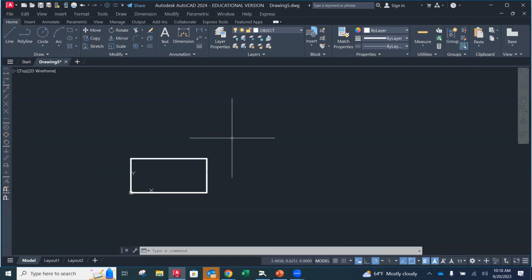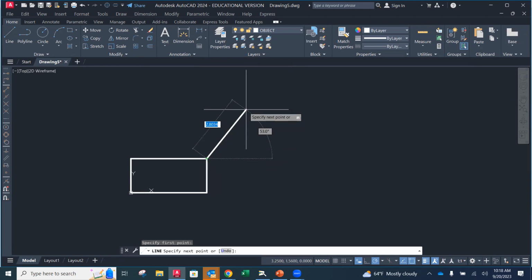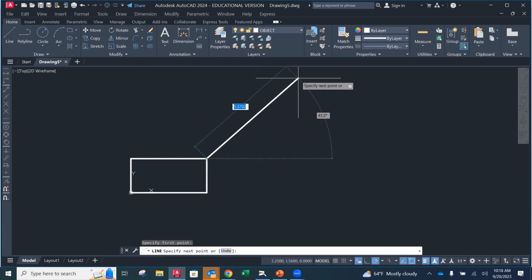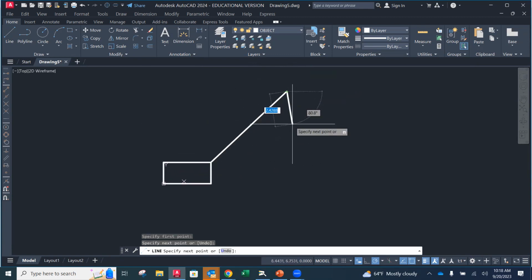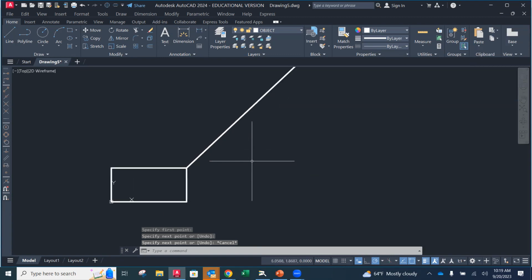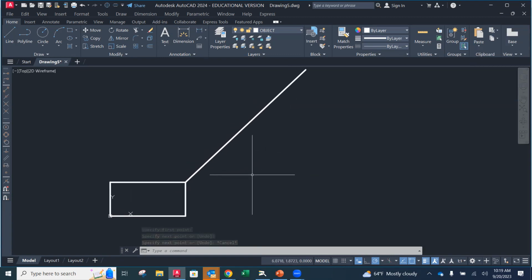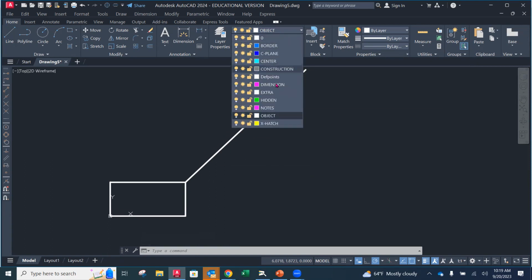And then what I'm going to do is keep my miter line as an object line just because it's the miter line. And then I'm going to delete it when I'm done. When you hand these in and you do the drawing, those come off. So we always are going to hide construction lines. I'll be using those soon, but I feel like a miter line, I want that to be something that sticks out when I'm doing my construction. So I'm just going to do my line. I'm going to grab the endpoint here. And then when I get close to that 45 degrees, it's going to snap. Okay. And I'm just going to come down a little bit, and make sure that it's going to be long enough. Okay. Random length-ish.